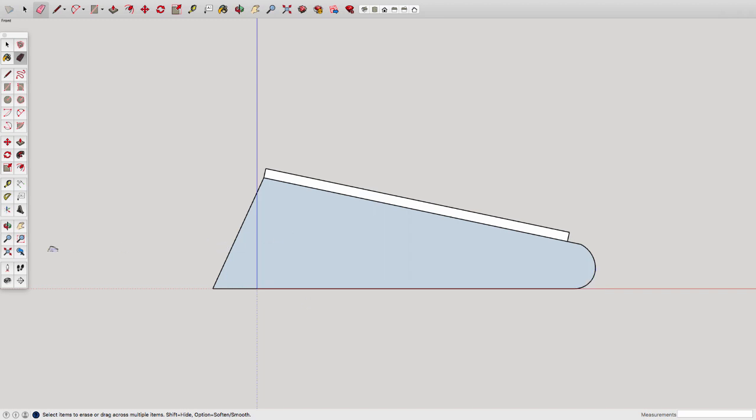Okay, cool. Arc tool again. A on the keyboard. I'm going to have a little rounded back section here because curves traditionally in woodwork are hard to make, but we have the luxury of a laser cutter here, so that does all the hard work for us. So we're going to utilize those curves and make it look better. There we go. Eraser tool, delete this line. It's flat on the bottom. Flat on the bottom is good because it needs to stand up nice and flat.